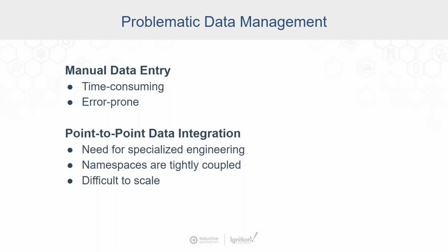So, this is Modbus register 40,001. It has a value of 12. Well, what does that value mean? So then we have to go in and edit where that tag is coming in and say, well, actually, this is an analog value 0 to 1024. We're going to scale it 0 to 5,000 somethings. Oh, those somethings are going to be in PSI. And we might want to enter things like dead banding and things like that.